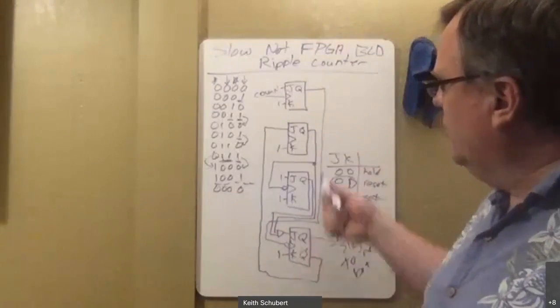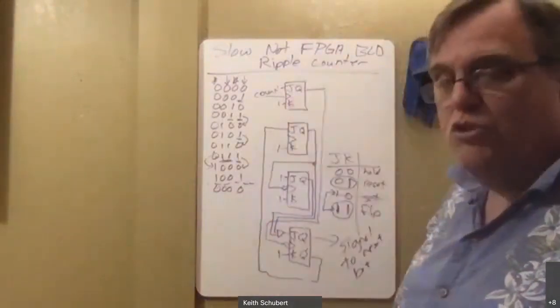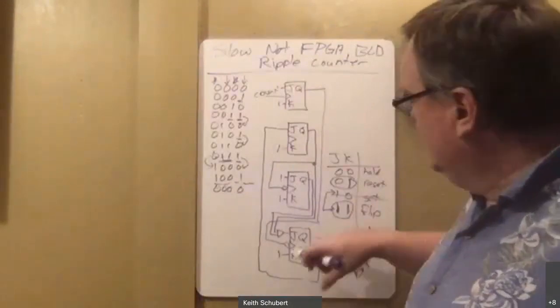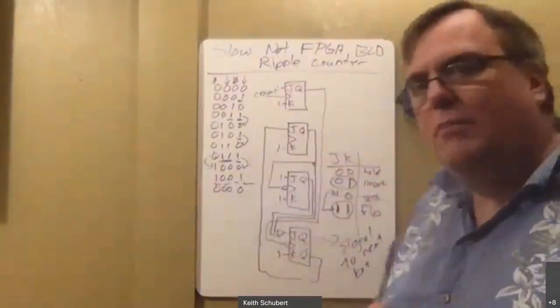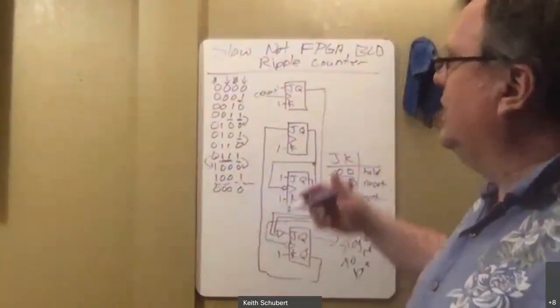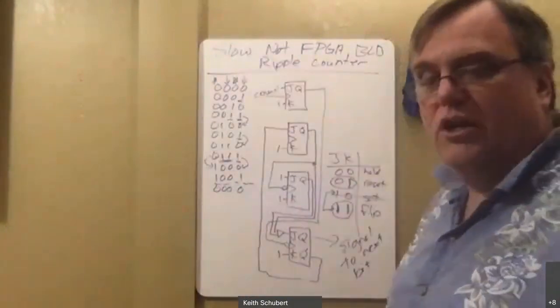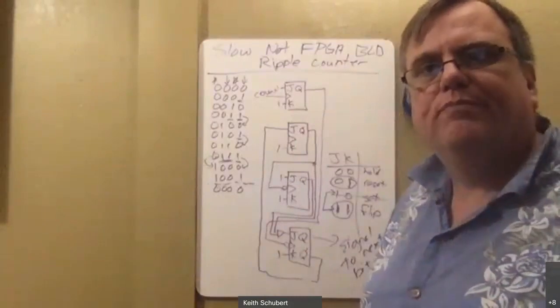This again, if you notice, I've got logic coming in here, so it'll ripple, it'll have skew to it. And that means this output signal has to go through 4 of these blocks with some feedback, right? This is slow. So as long as it is a slow signal, you're good. If you get to a fast signal, this is doomed to fail.